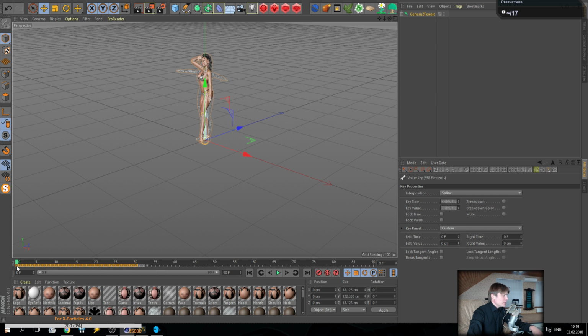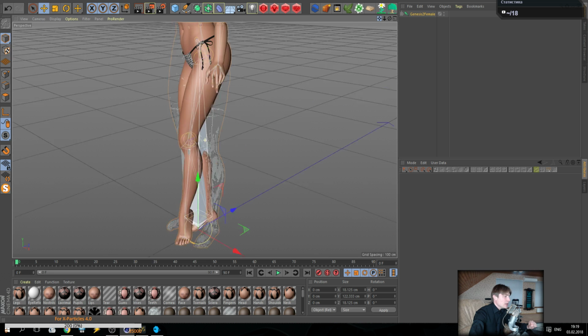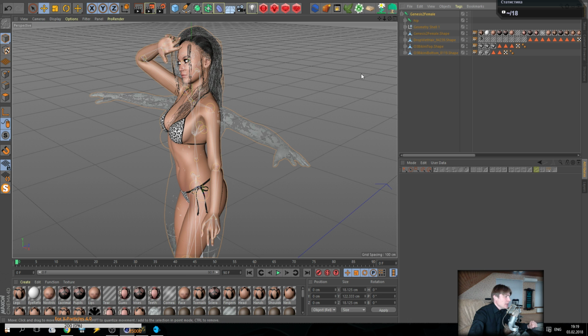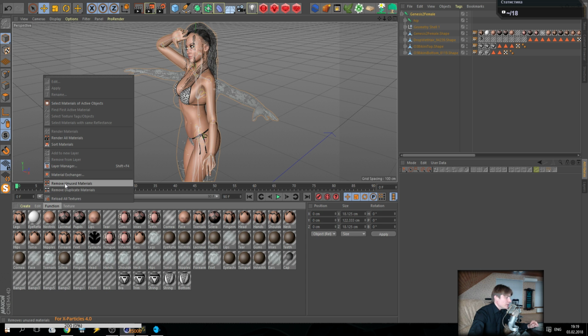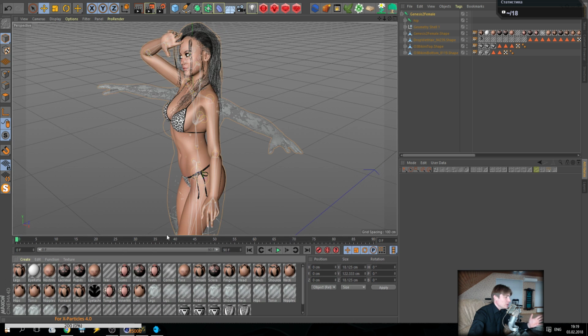So it's also transferring with some animation. Just delete it. We don't need it. And what's the problem? The first problem which I found just a few days ago. Look at this. Open Genesis, and as you can see, during transferring, you can find some problem. Okay, first of all, as you can see, many materials are coming. So go to Function and remove unused materials like this, because some additional options came that we don't need.